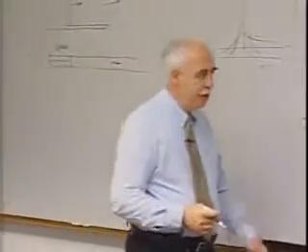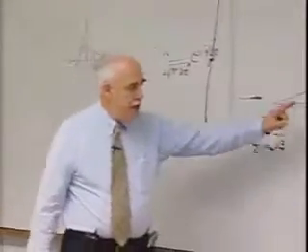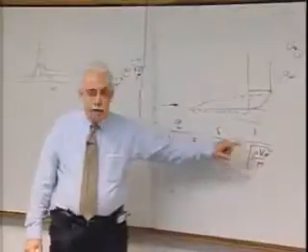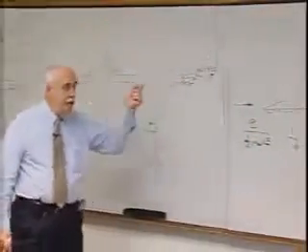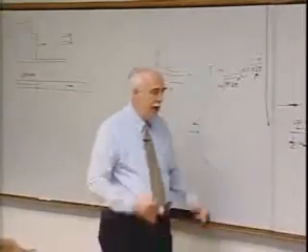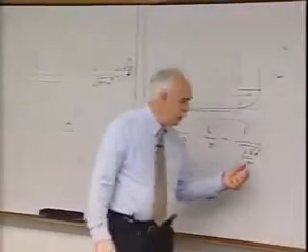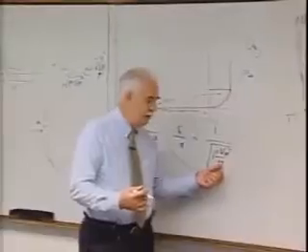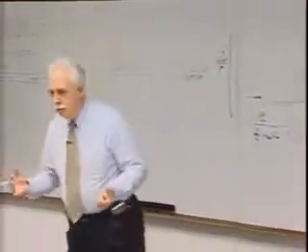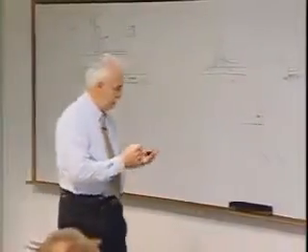Very important because heat transfer is basically inversely proportional to the square root of Reynolds number. Okay? So we've got square roots showing up in the thermal diffusion, we've got square roots showing up in the heat transfer. Now, when you put in the effects of real viscosity and everything else, there's a little variation. But first order, that's the behavior that we're looking for.